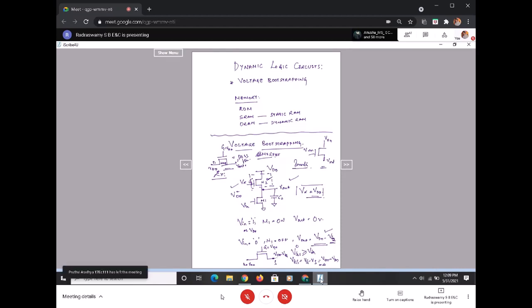Now, if I take this as my source voltage, VGS greater than or equal to VTH, where VGS is VG minus VS. VG is still at VDD. Now VS is VDD minus VTH. This cancels, minus into minus becomes plus, VGS is equal to VTH. Is this expression true? Then only I can say NMOS is on. Information is passed only when the transistor is on, and for an NMOS, when drain is at VDD and gate is at VDD, the output will be VDD minus VTH.